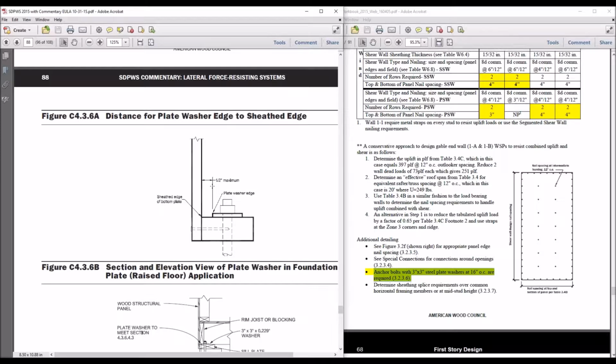And so the detailing has got to be such that you're always within 1/2 an inch of your sheathing on the outside. For a 2x4 wall, it's real easy. For a 2x6 wall like here, you're going to have to offset or use slotted plates to make sure you can get out to within 1/2 inch of that wood structural panel.